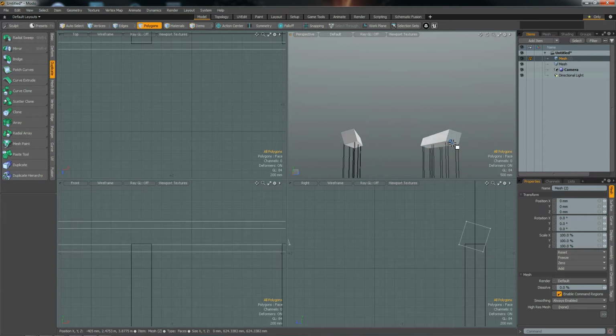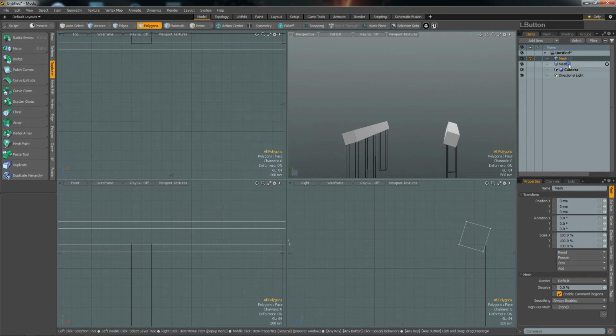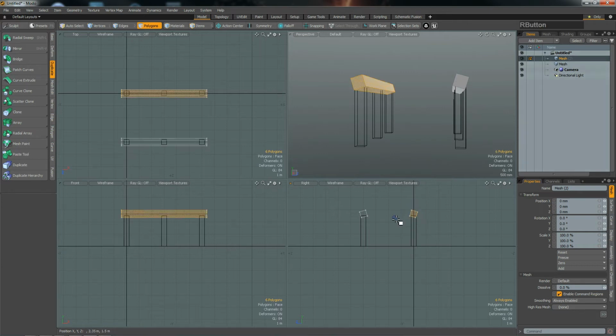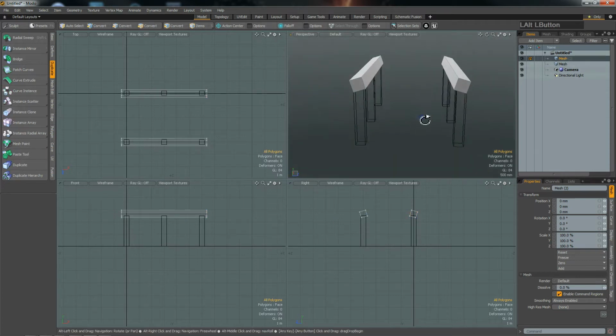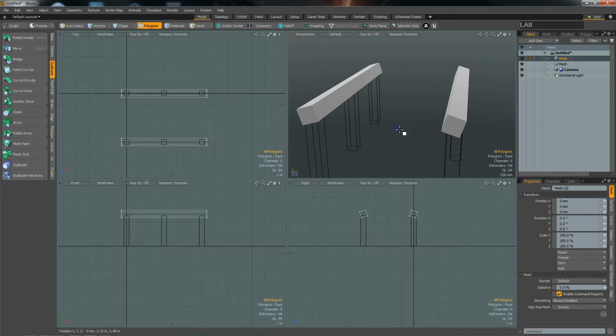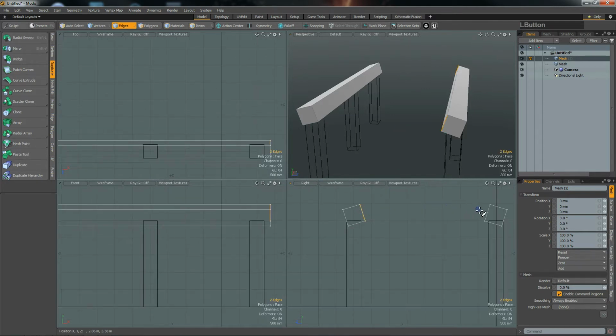Now we could already combine those elements with each other and then bool it against this, or we could have just created one row of items and then taken the other one from the roof, bool that together and then mirror the entire structure. There are many ways of doing it. What I tend to do is to push the Boolean operations very late in that process, to have more options, because you could also iteratively bool, so taking the Boolean result and then bool that against some other things, or use that as a cutter for a subtractive Boolean.